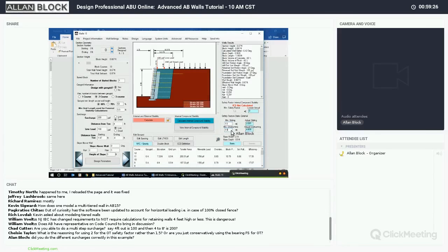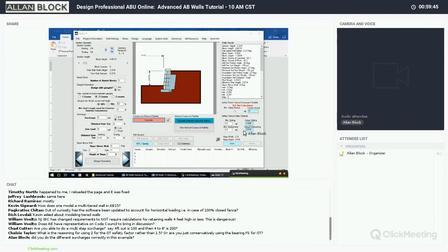Any of our safety factors in here are just recommendations, we default to 2.0 because that's what the industry recommends. But if I'm truly doing a gravity wall, if I come back to that low wall, 3 feet, maybe no surcharges, and I want to calculate that without grid, I can use that and check to see if that works with a 1.5 sliding. And in this case, 2.0 for overturning would have been fine as well. But I can always double check that.